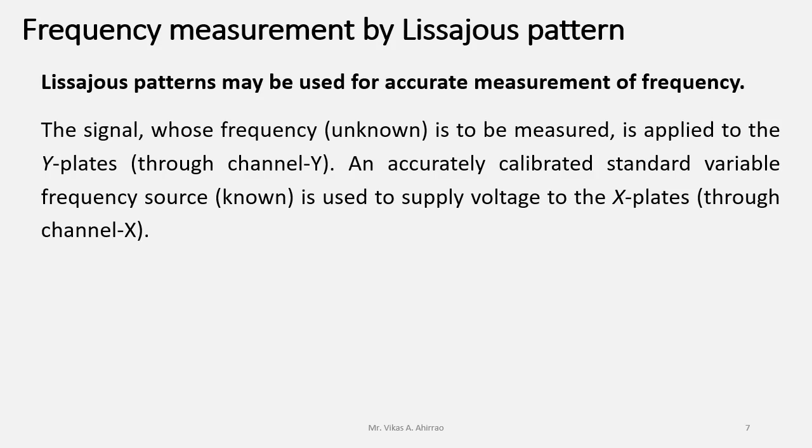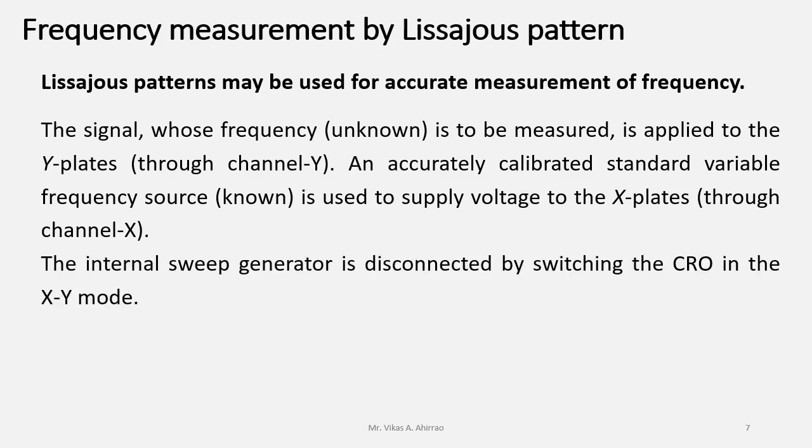The internal sweep generator will get disconnected, as to observe the Lissajous pattern we have to switch the oscilloscope to the XY mode.